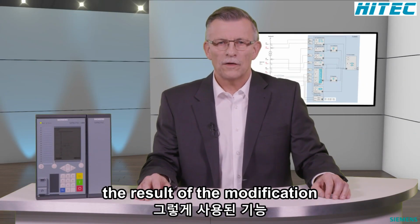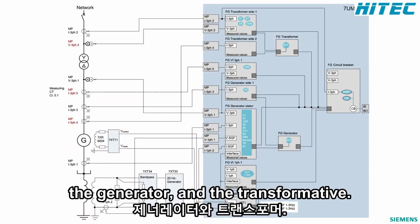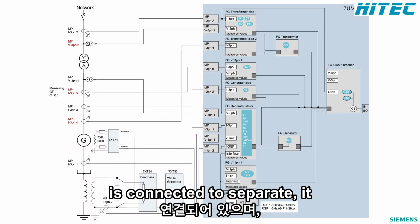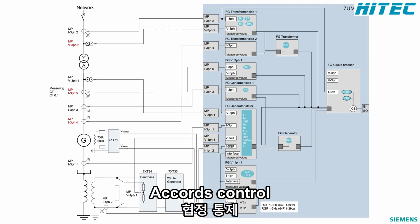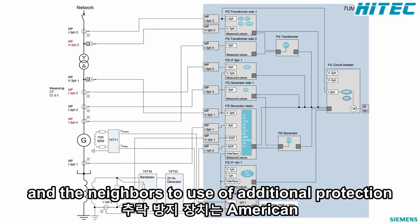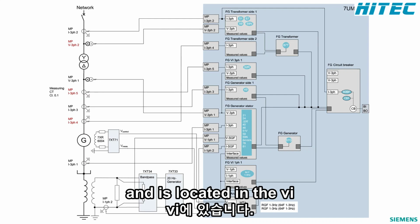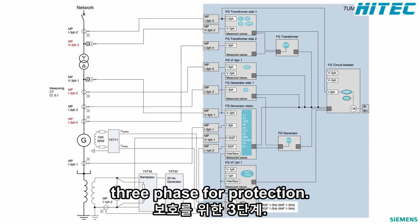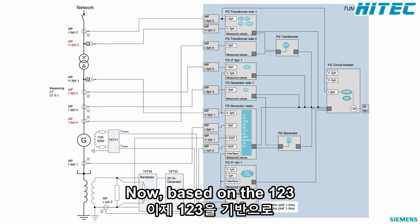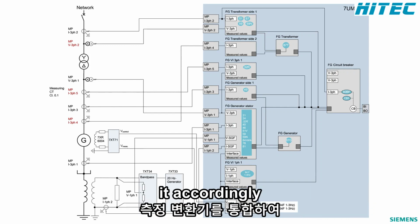The following figure shows the result of the modification including the used function groups. The generator and the transformer differential protection is connected to separate CT cores. The function group transformer side processes the voltage on the high voltage side additionally and enables the use of additional protection functions. The reverse power protection uses the measuring transformer and is located in the additional function group VI 3-phase. The rotor ground fault protection, now based on the 1 to 3 Hz measuring principle, has been adapted accordingly by